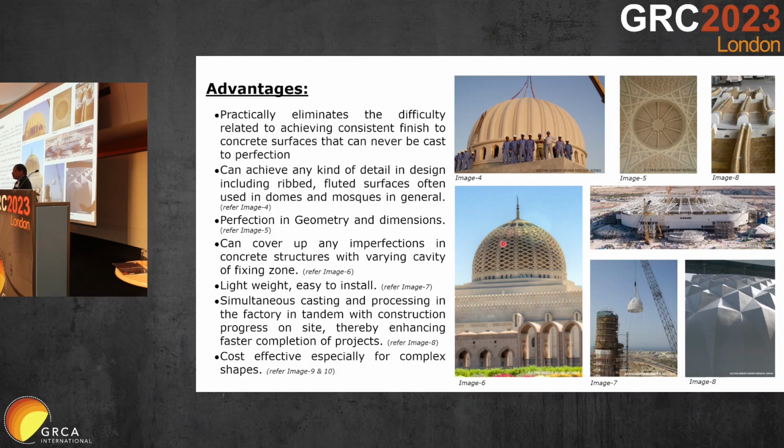As soon as the dome is cast, after the curing time and despite the regular site issues, we can straightaway start on the final finished product. This is the biggest advantage of using GRC.